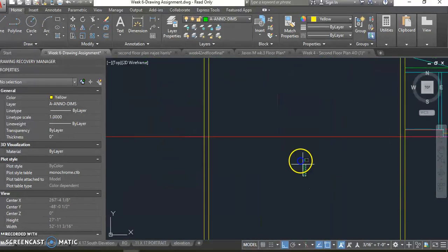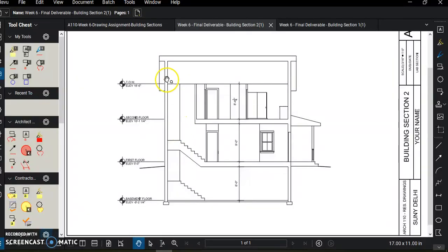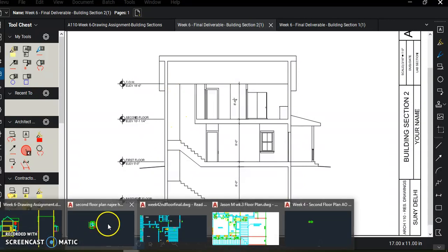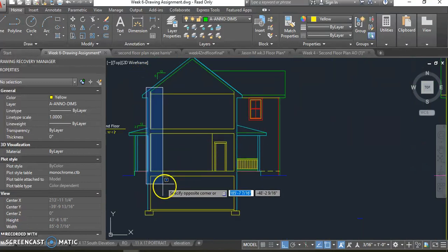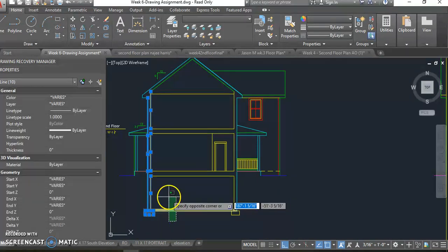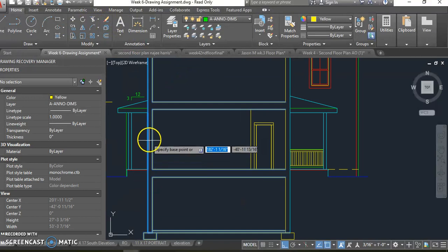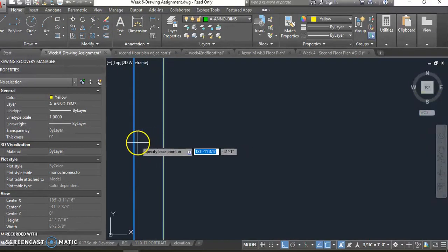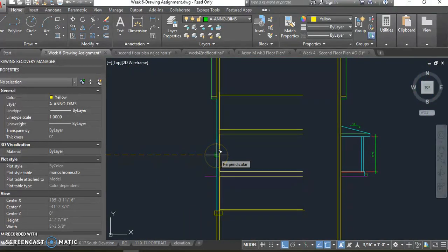Since I've already established and drawn some of the insides or reference lines in this section, I'm just going to copy now one wall of this section over to this one. So if we've drawn it nicely over here, I'm going to copy the whole wall, all the way down, footing. I'm going to copy this slab, only one side, floors, and I'll grab the ceiling as well. Copy, paying attention to the base point, which is the exterior wall, over to here, right on this exterior wall.